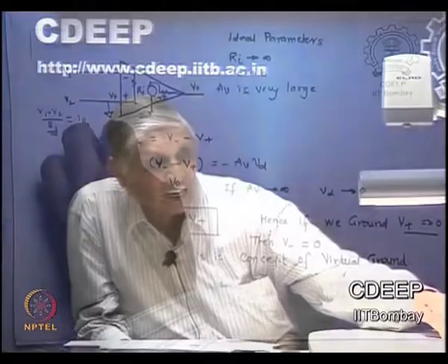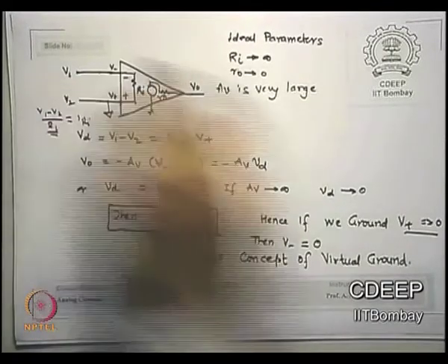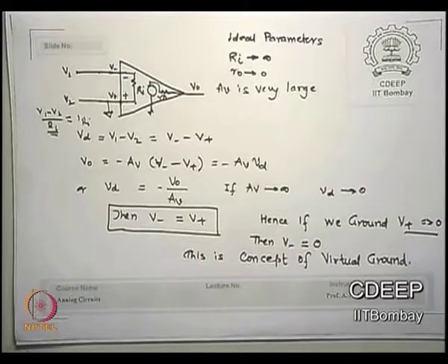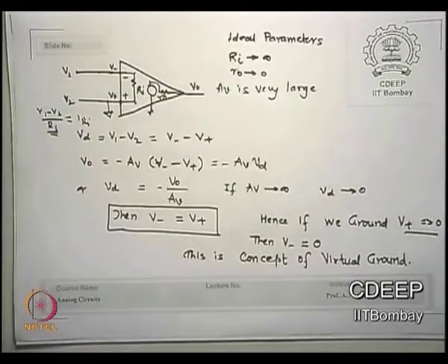Current must sink there, current is going to ground, so we say it is physically grounded there, therefore the potential is 0, all the current sinks there. However, in the OPAMP we said there is really no current flowing at V minus. However, these potentials are the same, because we say V plus is V minus.